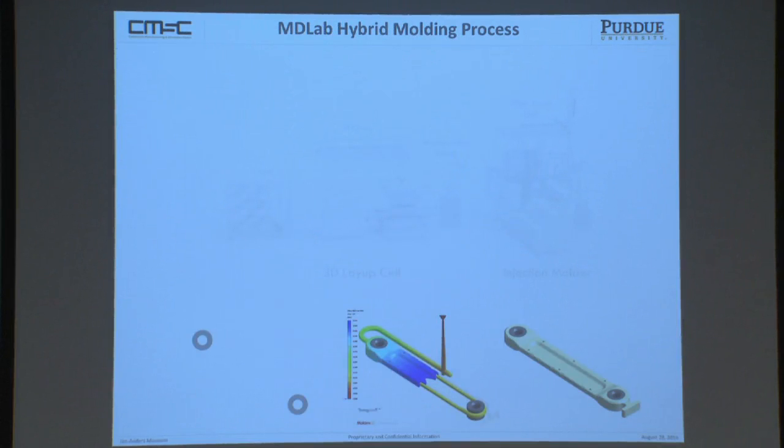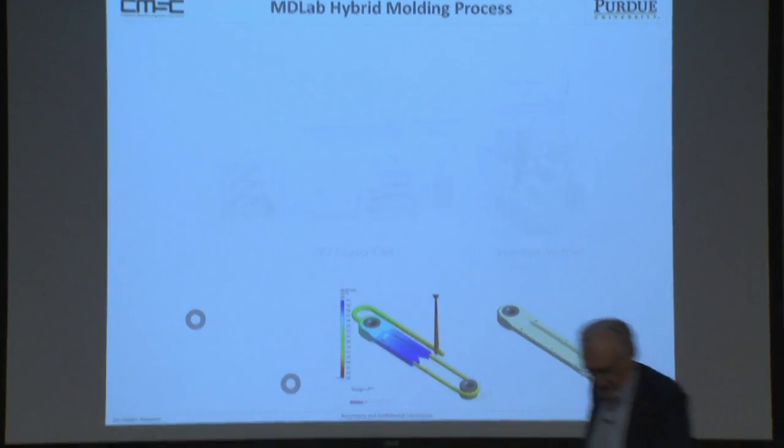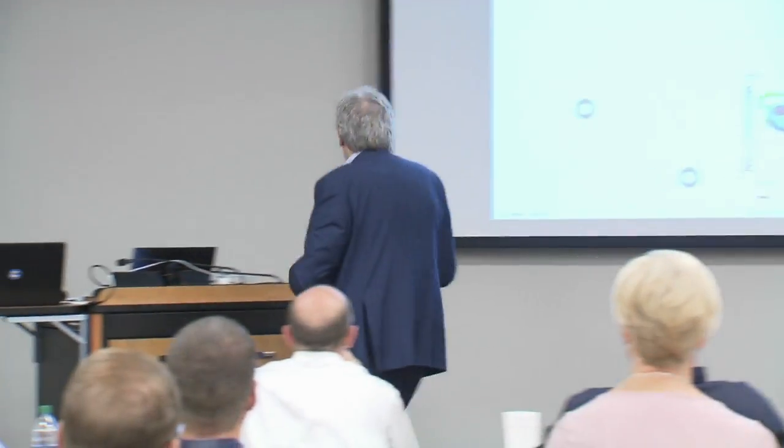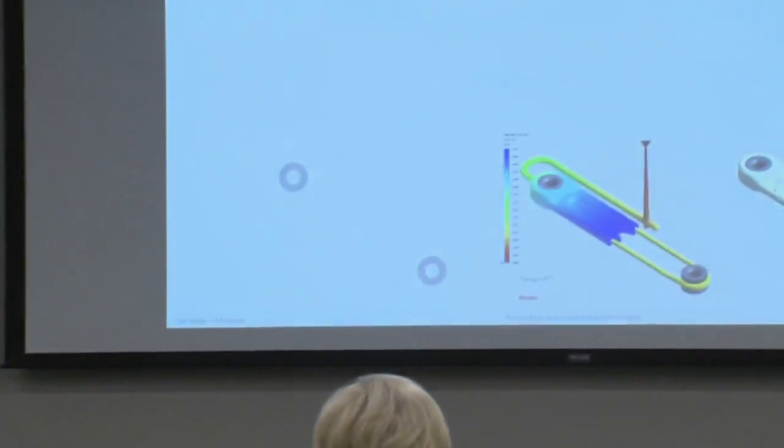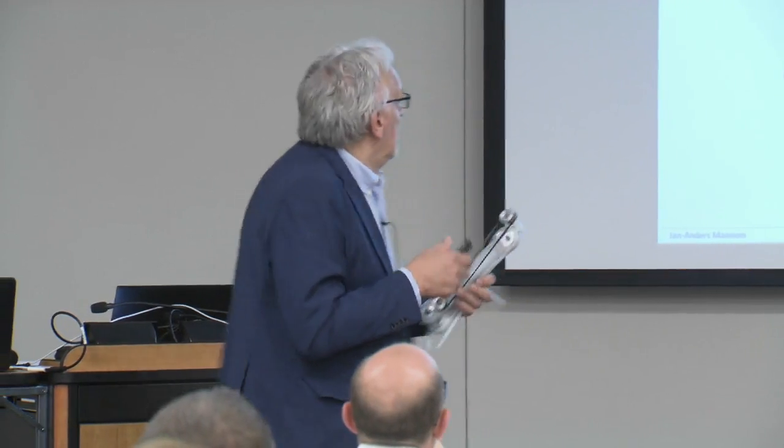I'm going to give you an example here. The test bed is just the other side of this wall, and I'm going to give you an example of a part that we are making there. We use that as a test sample. The question is how do we get continuous fiber into injection molding? Not a cycle time of 10 minutes, but 45 seconds. So first we have to put the carbon fiber around so we get the structure. This is now the full load-bearing structure.